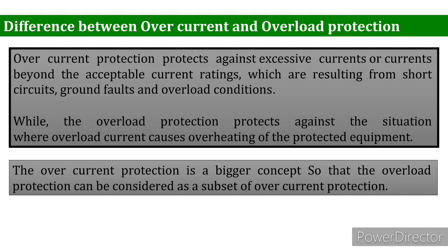Overcurrent protection protects against excessive current, or currents beyond the acceptable current ratings, resulting from short circuits, ground faults, and other conditions. While overload protection protects against the situation where overload current causes overheating of the protected equipment.